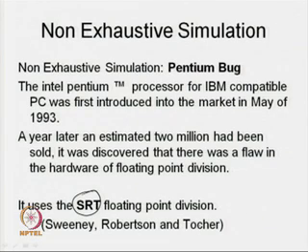Since it is a faster algorithm, Intel decided to use this division algorithm in their new Pentium processor. So, what is the difference? In this SRT division, we have to use a lookup table to find some output by looking at some input combination. They implemented this lookup table in their RAM, and due to an error in one entry of this lookup table, for some input combinations it gives an error. So this was the problem, this is the Pentium bug.